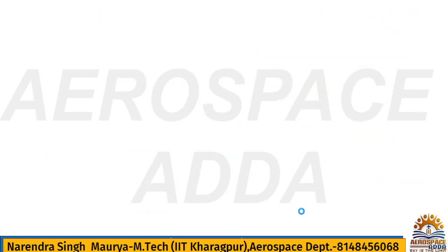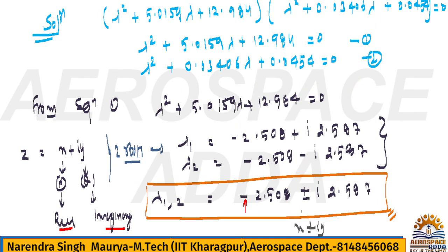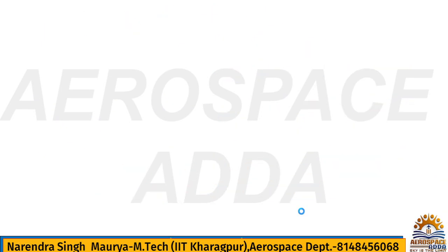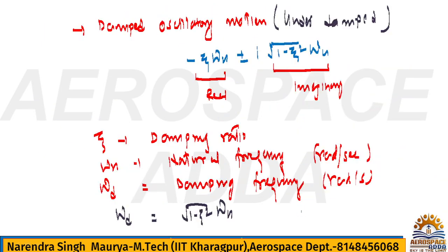You have to check, because as I have explained till now, the long time period oscillation is called phugoid, and the short time period oscillation is called short period oscillation. If the time period is very small, the natural frequency is very high, so it is called short period oscillation. Long period oscillation means the time period is very high, so obviously the natural frequency will be very low. Based on that we have to analyze. So we have two types of motion, and we are going to check one by one.